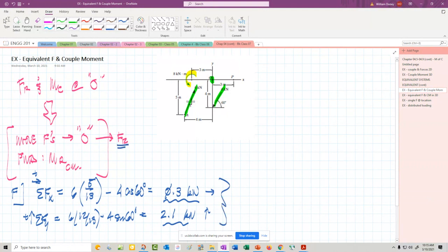Now I want to find the resultant force. I want to draw one force, so I take those two components and find the resultant from that, magnitude and direction. So the resultant is going to be the square root of the squares. If I go through that, this is 2.07. This one comes out to be about 2.1 kilonewtons. I changed that because you can't have 2.1 and 2.1 as a hypotenuse and one of the short legs.